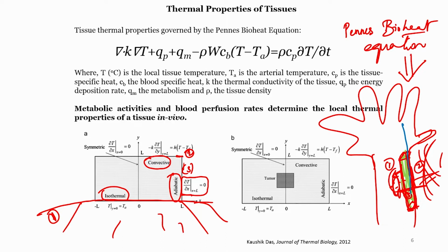That means that in this direction, if you go this way or this way, there is no change in temperature with distance, that is ∂T/∂x equal to 0, which is kind of like an isothermal adiabatic layer, right. So, that is why even in this interface ∂T/∂x at x equal to 0 is also equal to 0. So, that is the equation for the adiabatic surface.